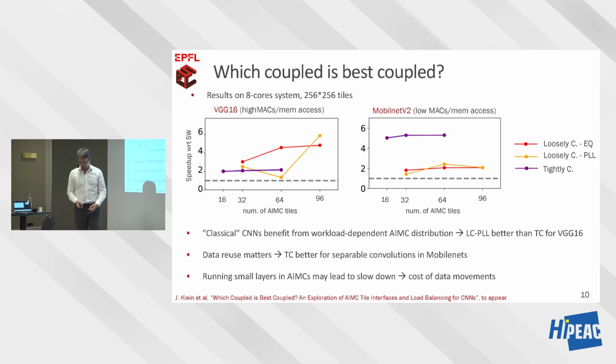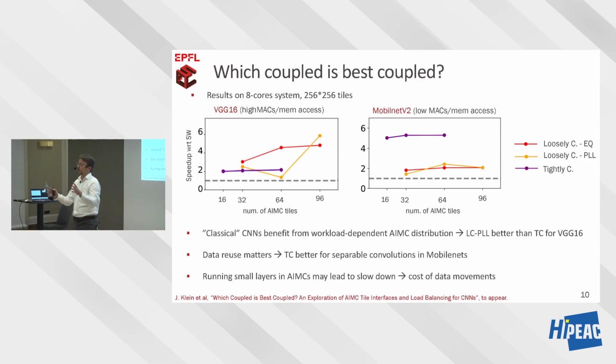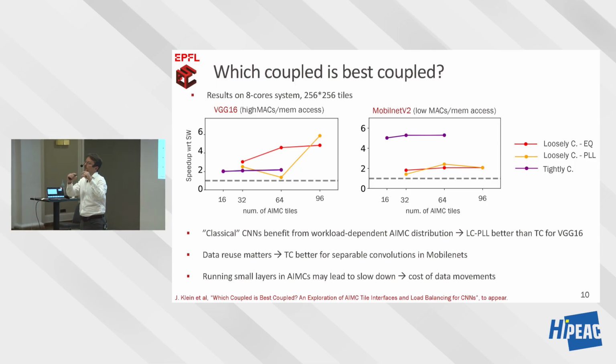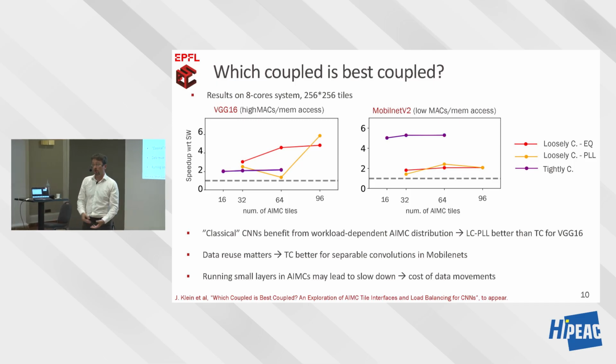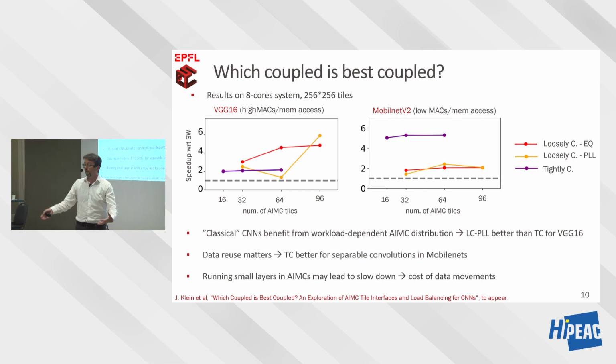This is because if you are using a crossbar, but just a tiny little part of it, the acceleration which we have by parallelizing the computation is not worth the data movements. So at that point, you would be just better off doing things in a normal way inside your processor and not invoke the accelerator at all.